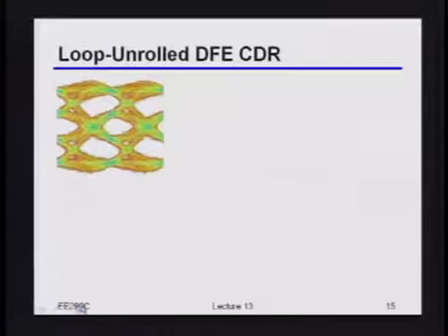So it turns out if you do a loop unrolled DFE, then your life is fun not just because of adapting the actual value of the coefficients for the DFE cancellation itself, but it has some pretty direct implications on the clock and data recovery as well. Okay? To see that, remember with the loop unrolled DFE, there are multiple possible analog levels going into your receive slicers, and that's indicated by this diagram that I'm showing you here.